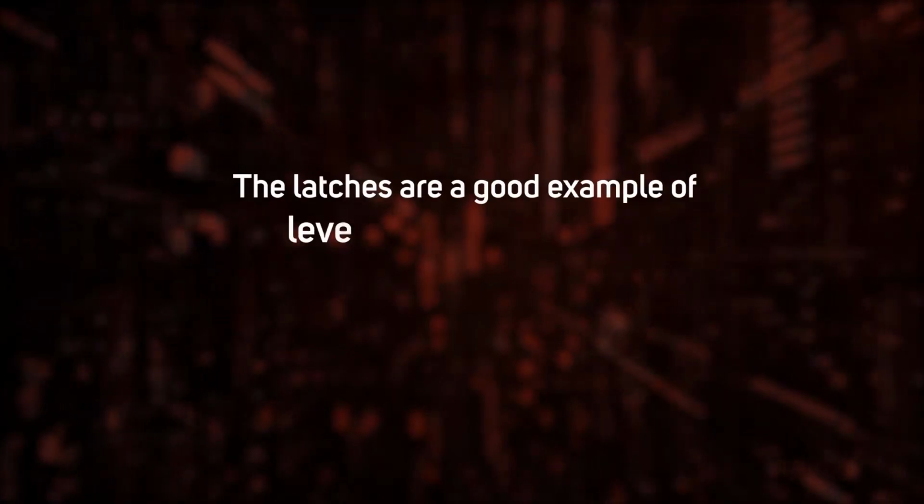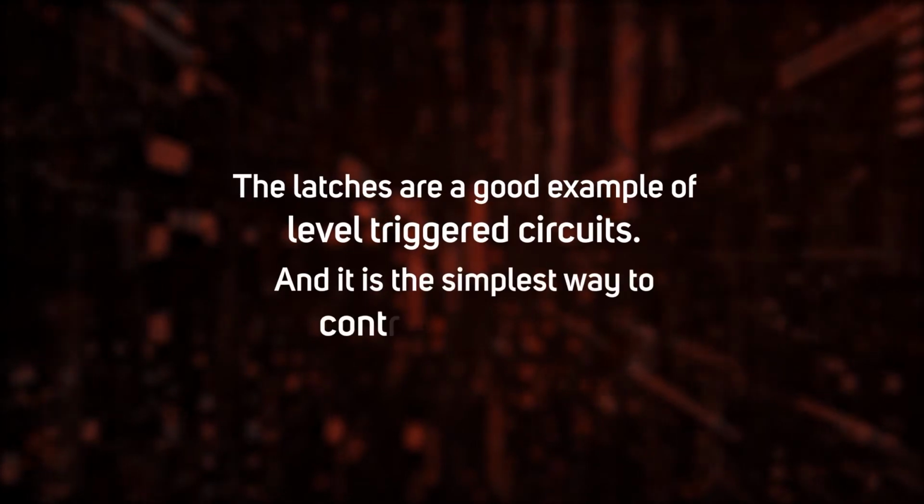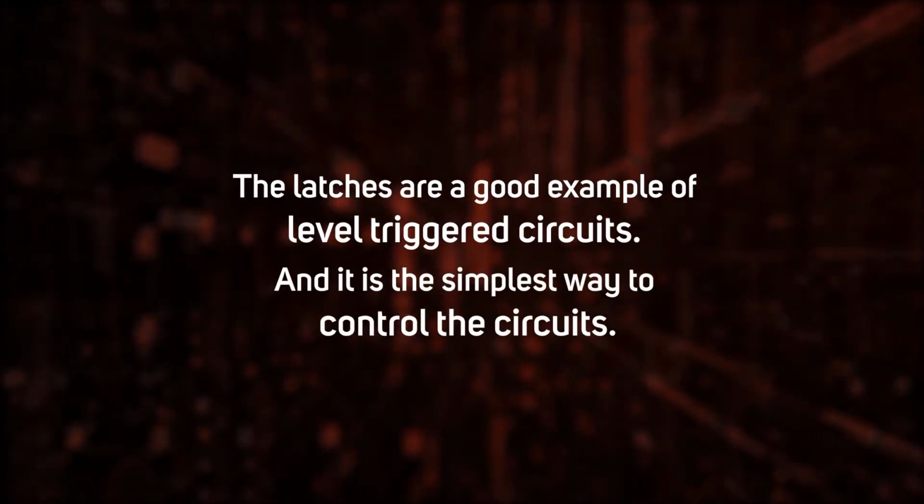If a circuit is triggered when the signal is at high or low level, it is known as a level triggered circuit, because only the two levels, high and low, have the power to trigger these circuits. The latches are a good example of level triggered circuits, and it is the simplest way to control the circuits.